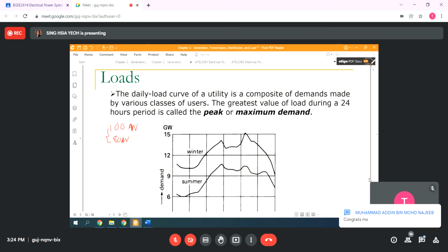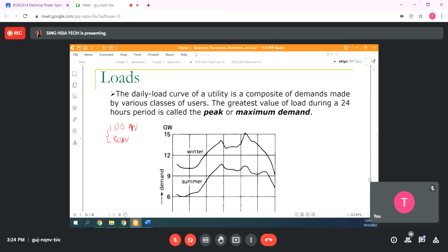Thank you, thank you. So back to the story. That's the reason the electrical consultant will need to discuss with the process engineer to know about the process of the factory, like for example how many equipments, motors, and all that will be used. Then roughly they need to calculate how much they will operate, for example 24 hours or maybe 8 hours a day. It's roughly, so you estimate the amount for this maximum demand.